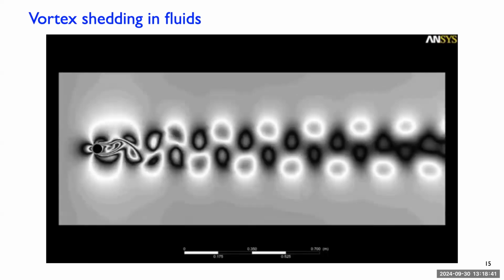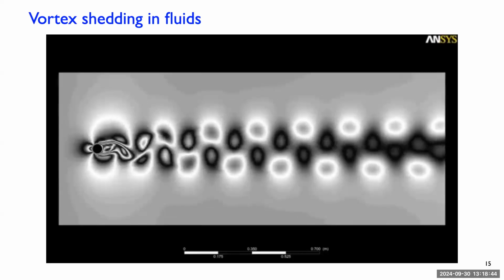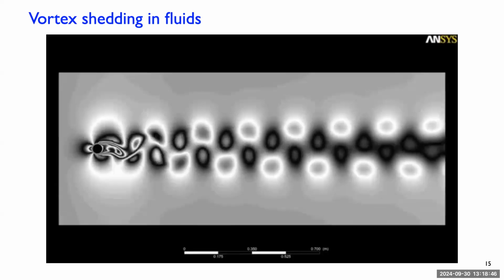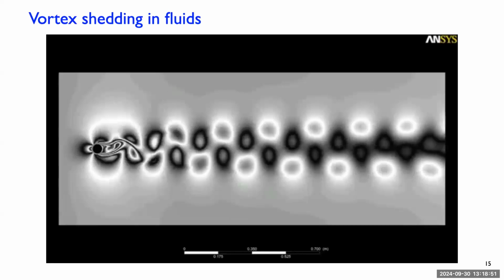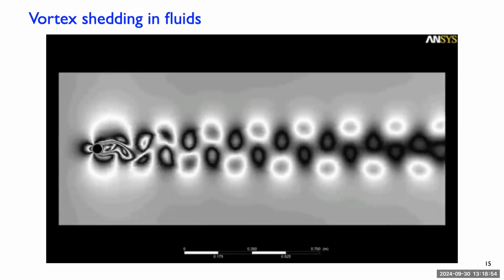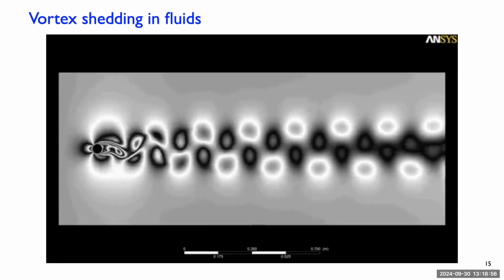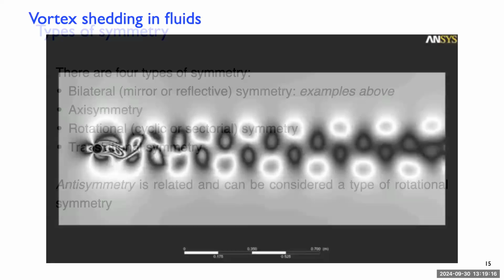It's like if you put your hand outside the window when you're driving in a car, you feel your fingers wobbling side to side. That's because vortices are flying off left, right, left, right of your fingers. We'll set up this problem. If you set it up perfectly, then the higher the precision of your computer, the longer before the vortex shedding will happen. You need a round off error to throw it off. But I think we set up the problem slightly offset from the top and bottom, so it forces a physical imbalance that, of course, sheds.